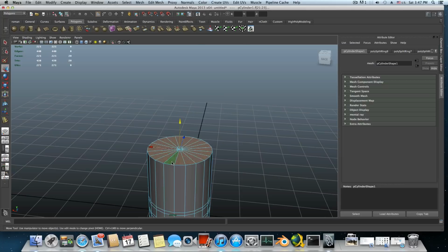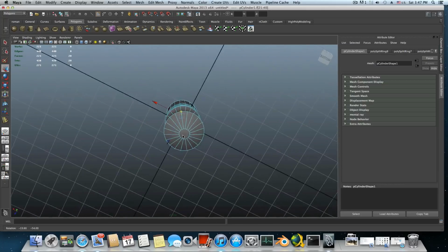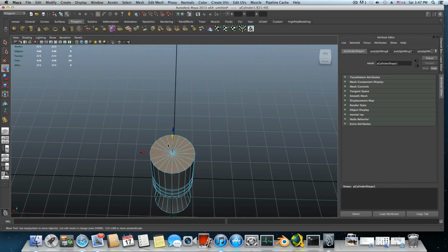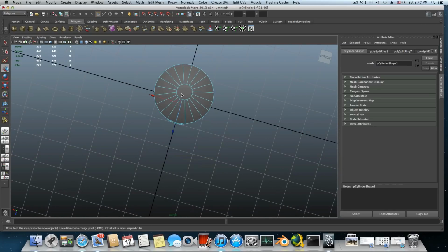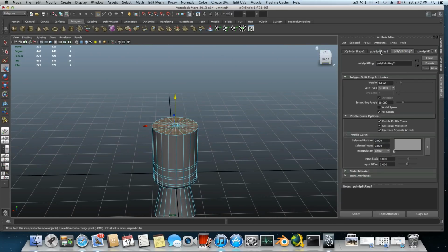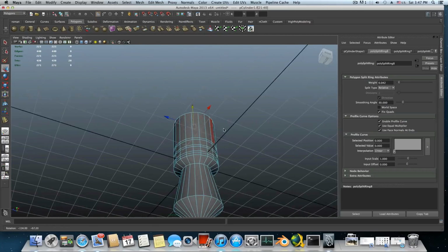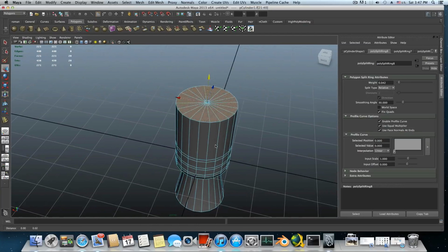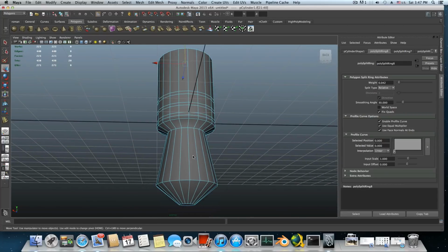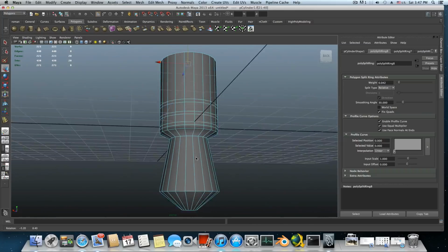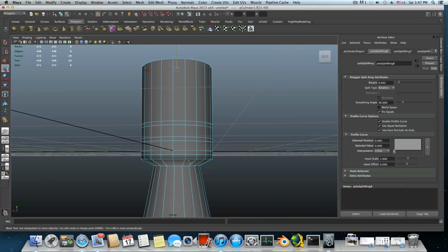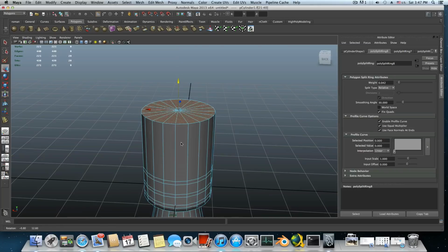Now I may have forgotten to tell you to do something at the start, which is to remove the cap, so it will look like this piece here, and also add more segments, so it will have 50 segments and look smoother. Right now it looks a little bit like pieces built from pieces, and I may need to apply smooth preview, but also to make sure I'm doing it right, I may need to apply more subdivisions here, supporting edges and stuff like this.